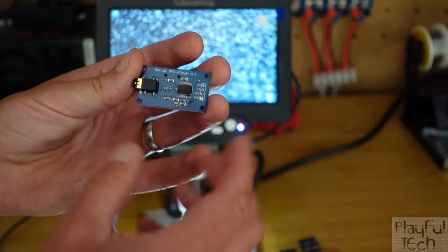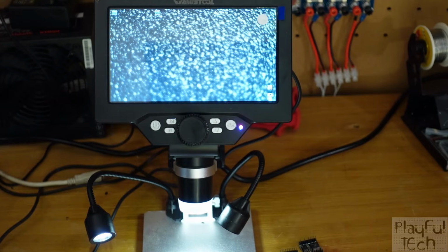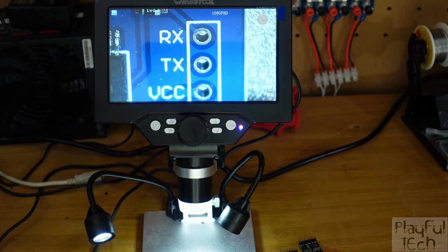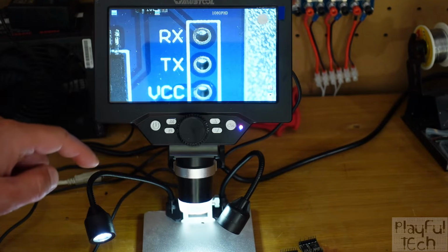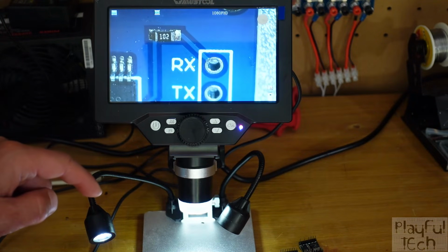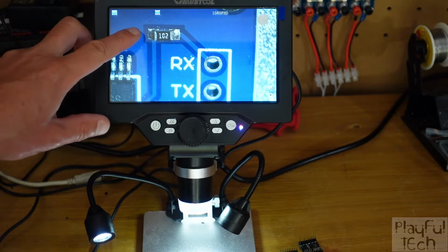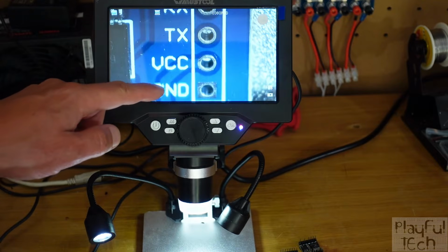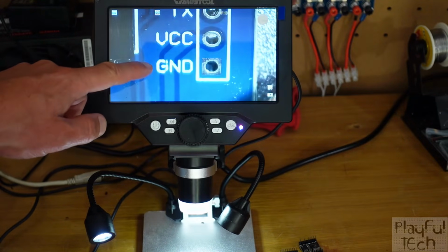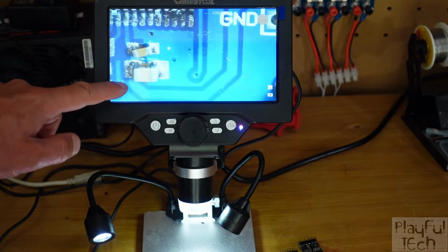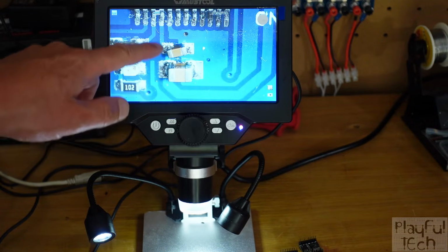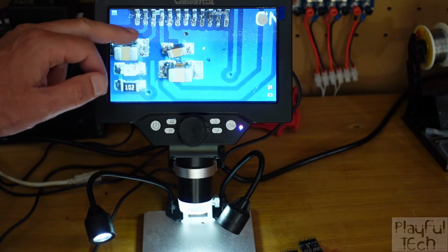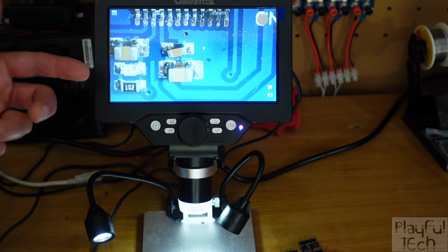So we'll begin with one of these serial MP3 player modules, and we'll take a closer look at it. So here we've got the interface, the 4-pin interface, and we'll see that the receive line goes via this built-in 1 kilo ohm resistor, as I mentioned. And if we follow the VCC line here, we'll see the trace comes down the board across through these 2 ceramic capacitors. This one's been slightly shonkily soldered on, but that will still work. And these are going to help smooth the power supply out.